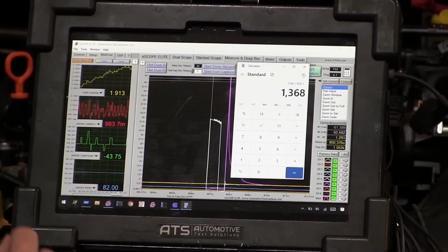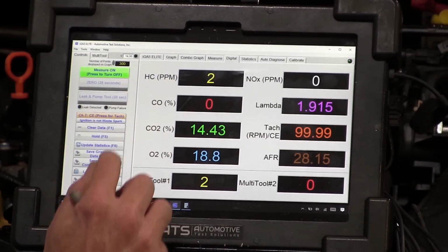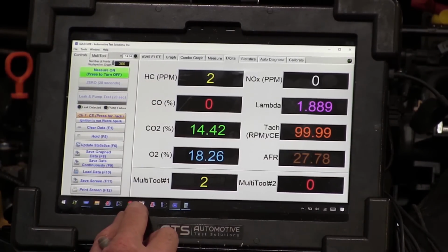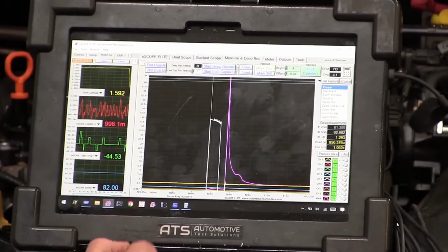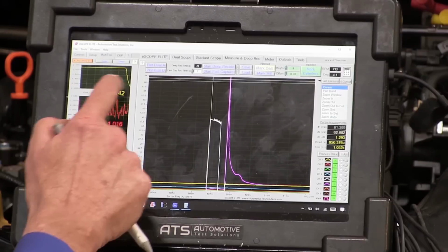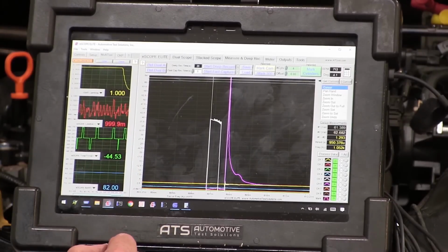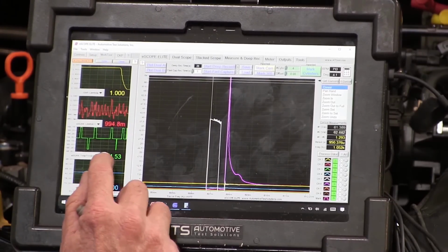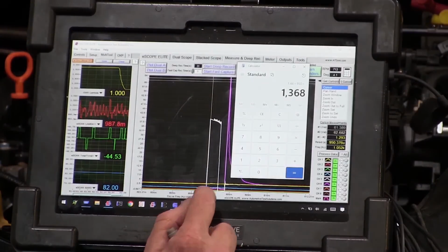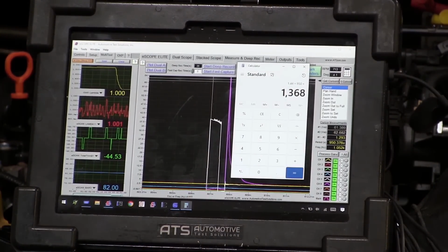okay, my lambda is going off right here. Let's go over here. My pump automatically turned off, so let me turn the pump back on here. The pump automatically times out in 20 minutes. So now we'll get the lambda back on because the pump will start pumping it. And we'll see that the lambdas match, 1 and 1. I'm still taking away 44%. Okay, so that's my injector on time that's calculated by this PCM for on time. Now this is idling engine, guys.